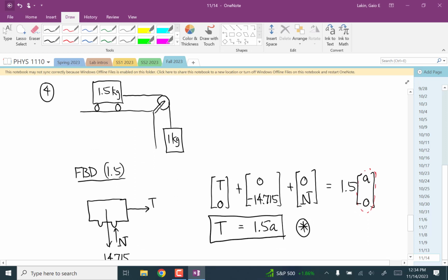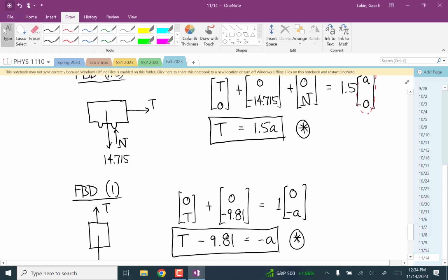So the answer is, I didn't have to know anything about the direction of the accelerations. All I'm figuring out with those signs is the relative direction. If one's going positive, the other one's going negative. If this one's going positive, this one's going negative. That's what you're doing when you find the direction of that second body's acceleration.